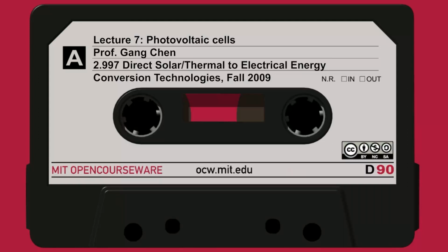The thickness of ITO is what? I can see the number. ITO here is about 0.5 microns. I'm not sure whether that's the best. People are optimizing. I just copied it from somewhere to show the relative scale. So people are doing transparent conductors, also trying to improve the conductivity. Basically, you want it very highly conductive. If you're highly conductive, thinner is better, because the free electrons in this material also absorb photons, which generally you don't want.